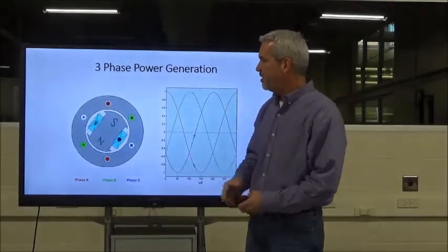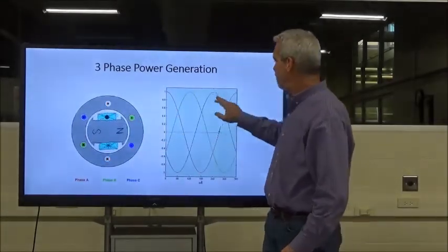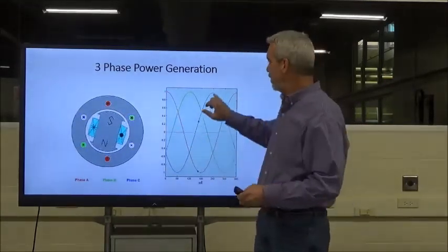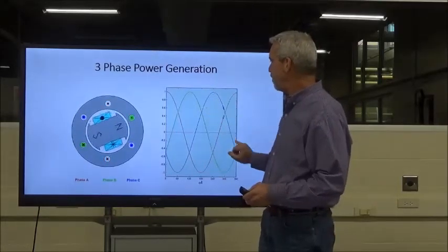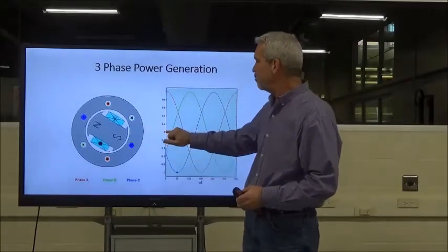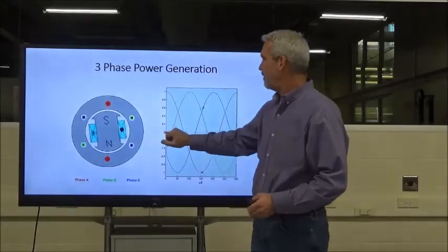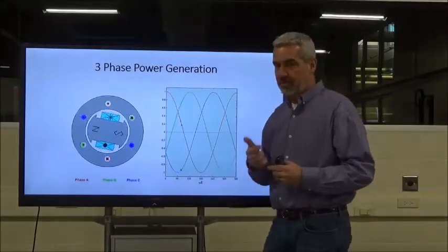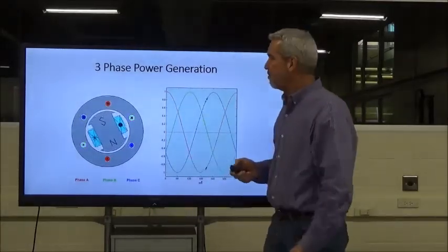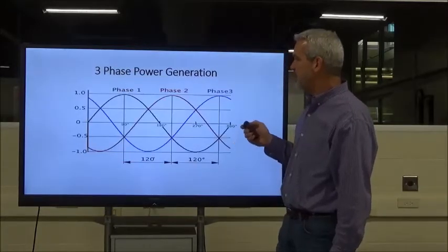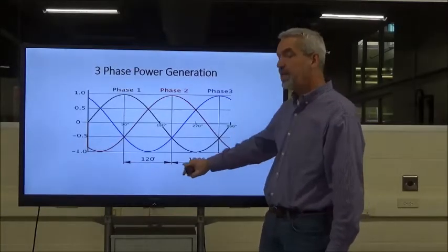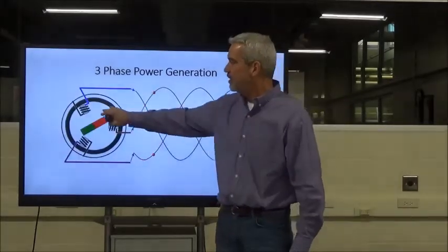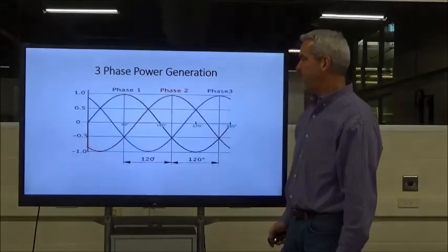You see the rotation and the magnetic fields as they pass the coils. It peaks, and it directly aligns with the coils. It peaks with these, and aligns with these sine waves, and these sine waves peak right there as they align. If they're 90 degrees out of alignment, it's going to be along the zero plane, producing no voltage at all. So that rotation is what we're looking for. That's what helps create the 3 phases. Just another example. There are the 3-phase sine waves, and notice again, this is very important, 120 electrical degrees. That's because our coils are 120 electrical degrees apart from each other.